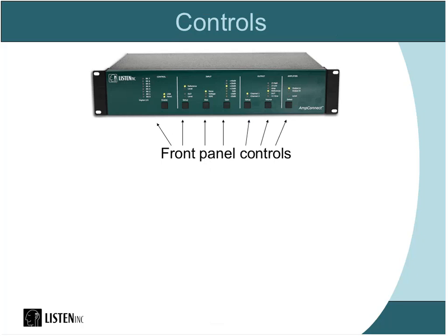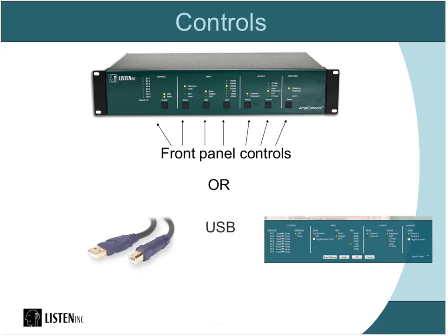But if you do want a little bit of control and really integrated automation, then you have the USB option. So through SoundCheck, with this nice little interface that we've built, you can send all of your communications to AmpConnect directly and write it into your test sequence. So this allows you to make changes on the fly, like during the sequence. If you want to have different settings at different parts of the test sequence, you can configure this little application to make the changes as you go.